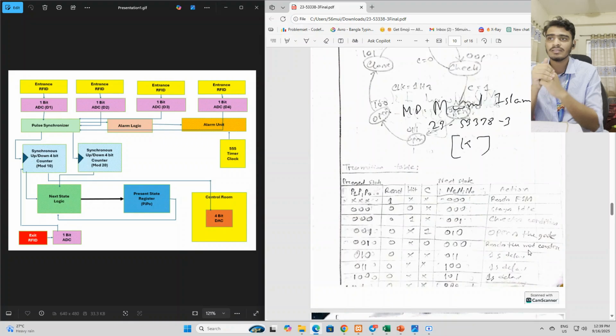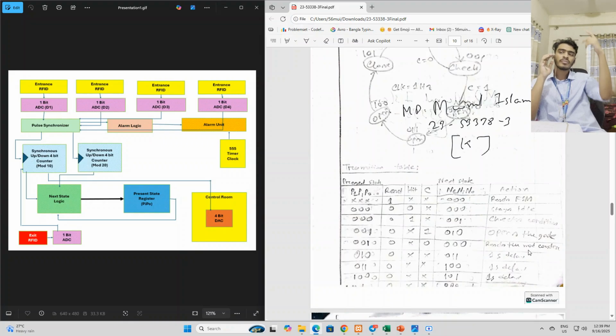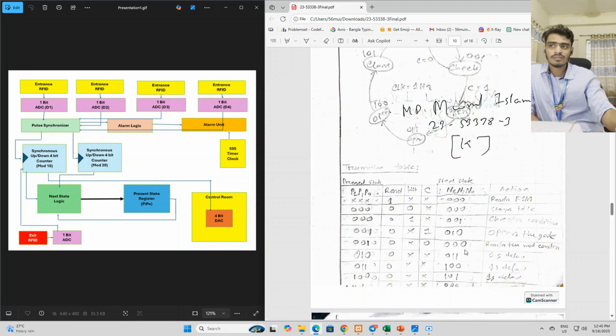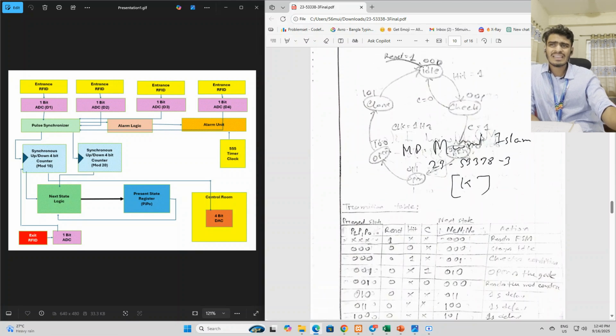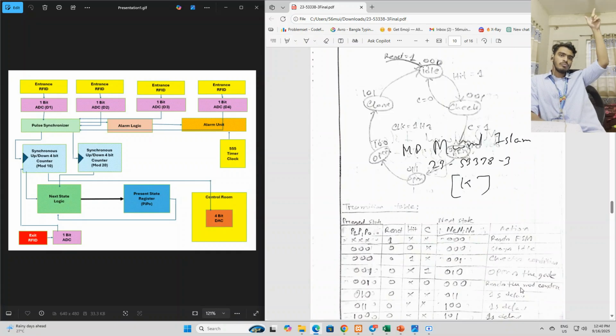Then there comes the thing. I've told you that the mod counter goes to 0 again. So if someone tries to enter again, it will count it as 1, right? So that's an issue. We need to reset the mod counter back to 9 actually. So in the state where the check is failed, it is going to idle again, and we need to perform an action based on this state. It will reset the counters back to binary 9 and binary 19 actually.